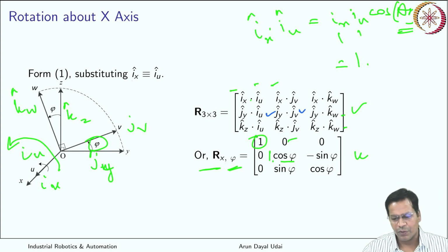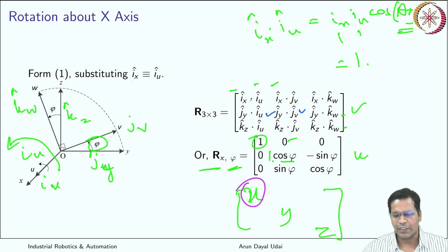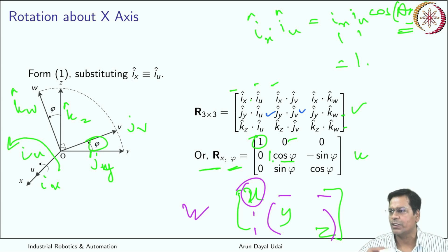There is a very good note over here. This represents x, this represents y, this represents z. In order to rotate about x-axis, you have to make this 1 and the corresponding row and column 0. This is the element which will have some changes that is to be taken care of. Otherwise, it looks like this. In general, this is so easy, recalling your rotation matrices. So this is rotation about x-axis by an angle psi.